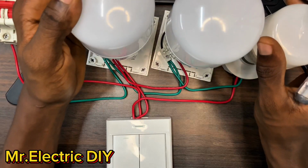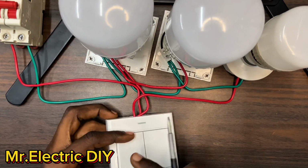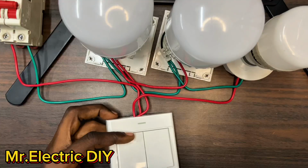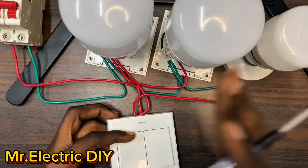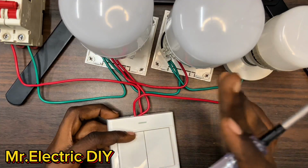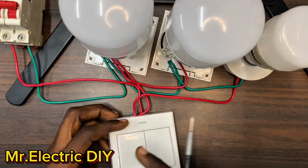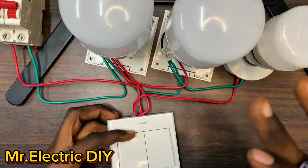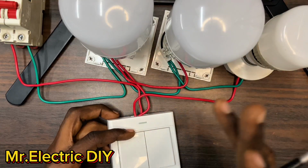If you want to control 3 lamps using 2-gang 2-way switch, and one gang is going to control 2 lamps at the same time, and the other gang is also going to control that single lamp, that is how the connection is being done. You can actually do this type of connection anywhere in your household. You want a gang to control 2 lamps at the same time, the other gang to control another lamp. That is how to do such a connection.